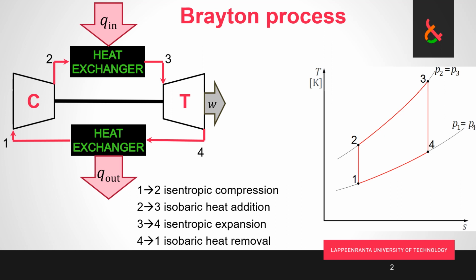The other thing is that because this is a gaseous fluid, we don't have the boiling part. So as we are bringing heat or removing heat, temperature is always changing. We don't have isothermal heat input in boiling or isothermal heat removal in condensation. And as this TS chart is very useful for us to understand the process and what affects the efficiency, we'll go through this as well here.